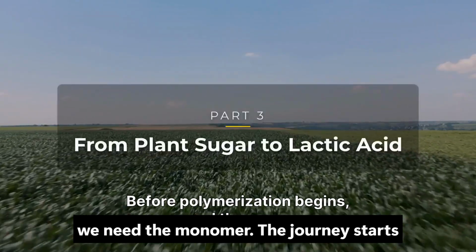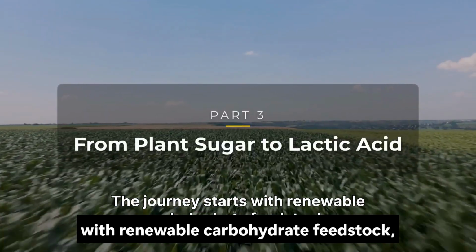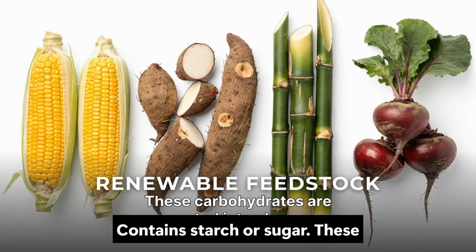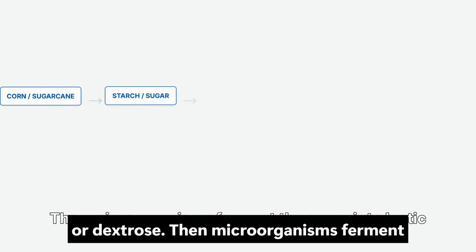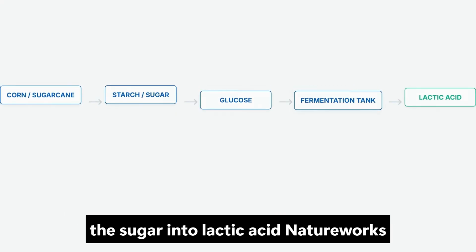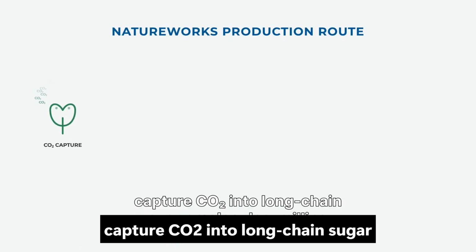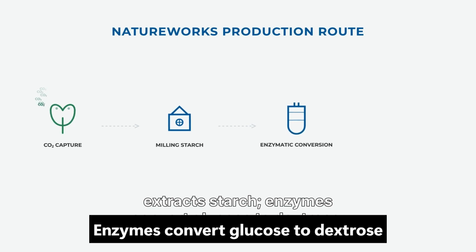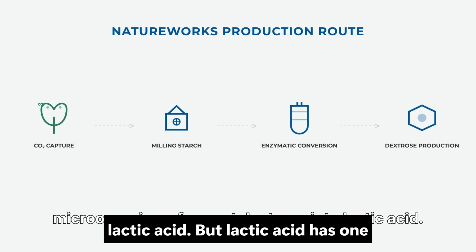Before polymerization begins, we need the monomer. The journey starts with renewable carbohydrate feedstock. Corn, cassava, sugarcane, and beet contain starch or sugar. These carbohydrates are converted into glucose or dextrose. Then microorganisms ferment the sugar into lactic acid. NatureWorks describes the commercial route as plants capture CO2 into long-chain sugar molecules. Milling extracts starch. Enzymes convert glucose to dextrose. Microorganisms ferment dextrose into lactic acid.